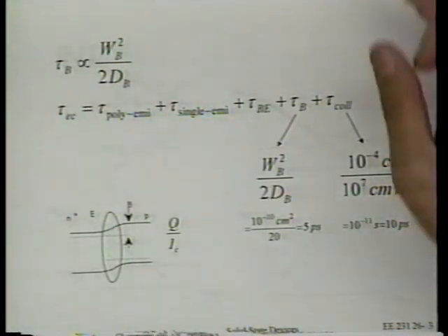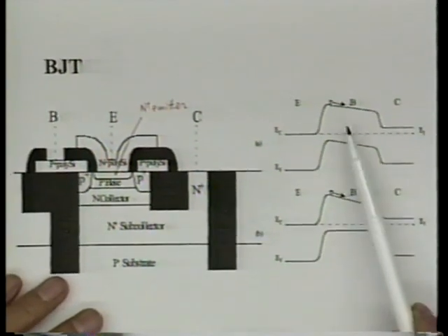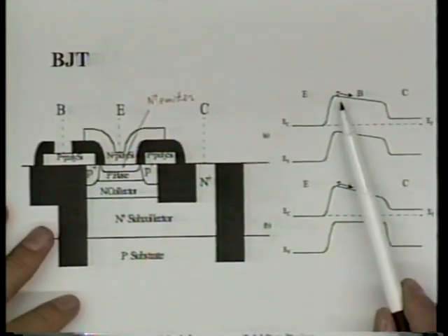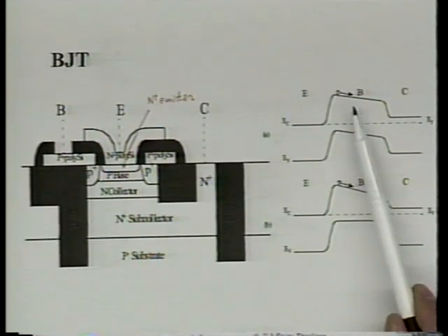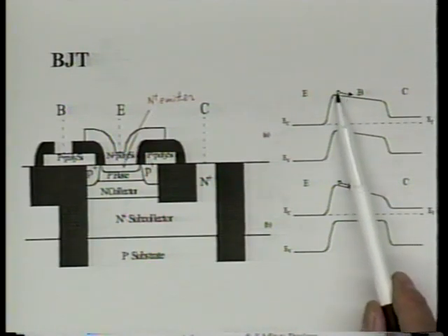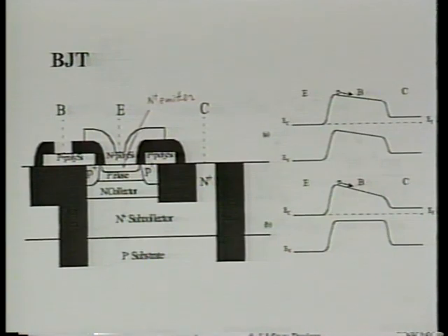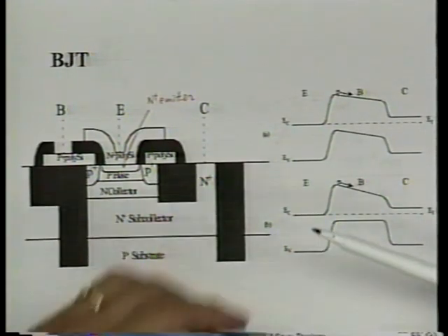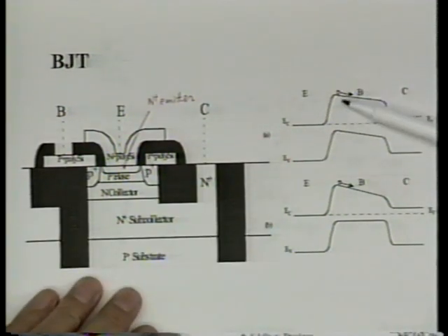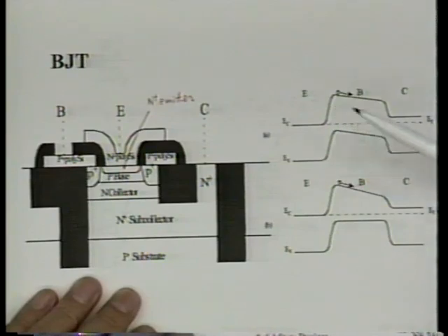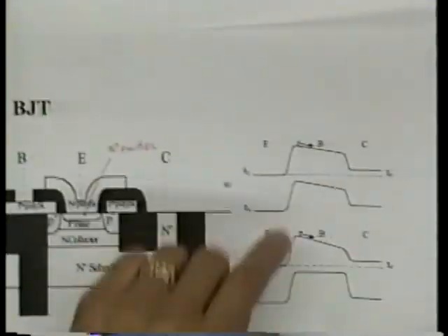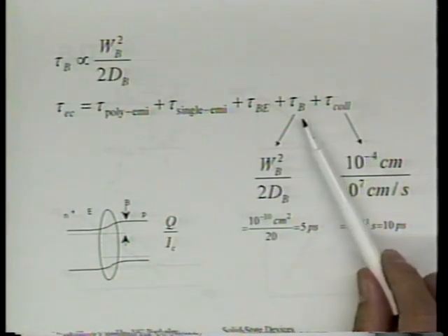We will have this energy band diagram, right? This is the base. Well, we're concerned about charge stored in the base, right? Tell me, where do I have more electron density, here or here? In the depletion region, where do we have more electron density? Right? So when we change the bias, we're changing the electron concentration in the base. We're also changing electron concentration here. And there are more electrons. But fortunately, the width is narrow, right? That's what we're counting on. So this is not negligible.